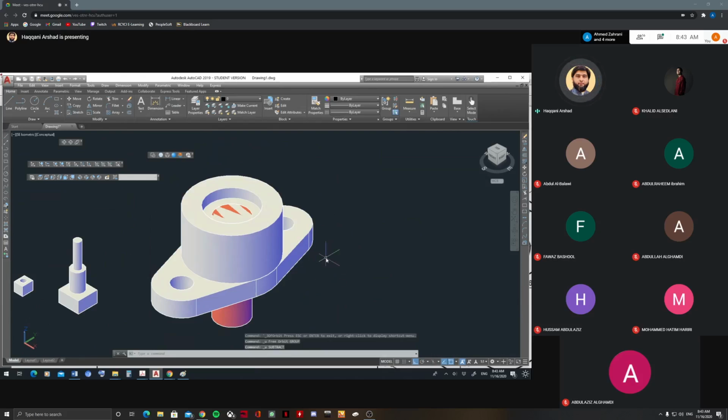See, when I go for subtract, I'll click the main body, that is the first body, enter, and if I select this one, then it will become a hole inside the cylinder only. So you have to select the base as well. So it will become a complete through hole. Enter, then select this one, enter.